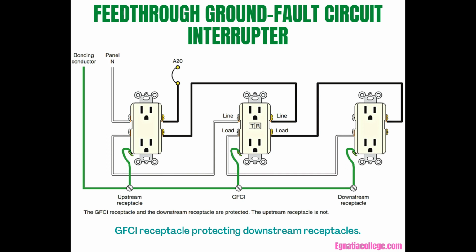A receptacle that is installed specifically for the washing machine in a combined laundry/bathroom is not required to be GFCI protected if this receptacle is located behind the machine and is not more than 600 mm above the finished floor.